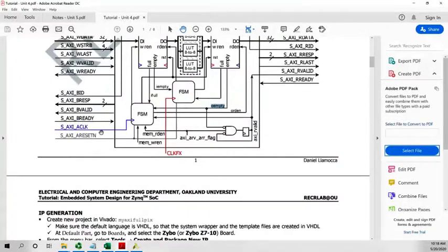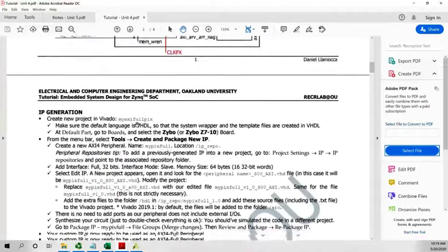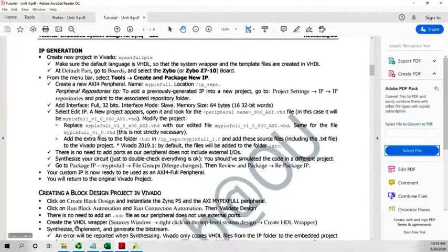And of course, like I said, in all of these designs, to make it simpler, we are just tying or connecting the clock effects to this clock, the blue one. I mean, ideally, this clock effects should come from a different source, right? But to make it easy in this example, let's just hook them up together. So let's create a new project in Vivado, my AXI-Full Pix.